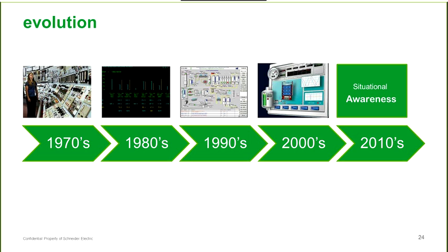Now, we at Wonderware have also been part of this. On one screen, you'll see our reactor demo. There you can see that we have a lot of big symbols on that screen that really don't give the operator much information. They're just occupying the screen and making it hard for the operator to read. So the next step would be situational awareness.